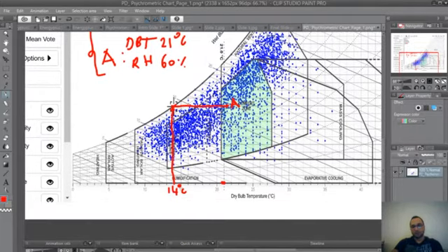For example, indoor air inside a building which touches a cold surface, as I mentioned, the glass, or within a wall or roof assembly, when the air diffuses through the wall or roof assembly by exfiltration. We are going to cover this soon. So water vapor condensation may occur within the wall assembly. So this is very important to know the dew point temperature of a volume of air.